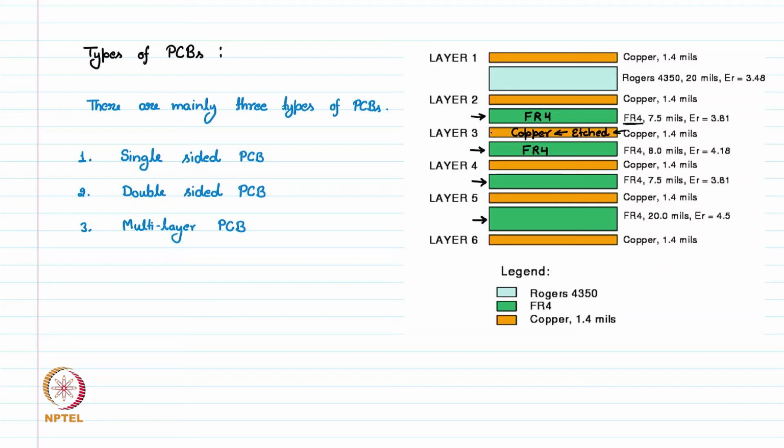However, they can be used to connect one side of an electronic component to another side. All these intermediate copper layers act as traces. So you have multiple FR4 here. If you see FR4 of multiple thickness, you can take multiple types of thickness and put them together. Now you have so many traces available. For example, this is one trace, this is this. You have all 5-6 layers of traces. You can design them as per your need and connect the electronic components together.